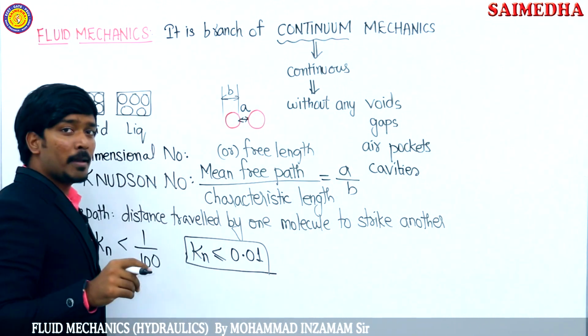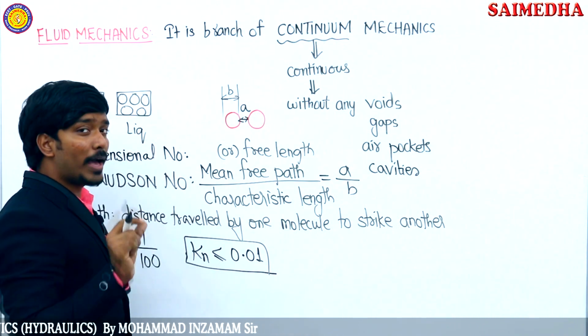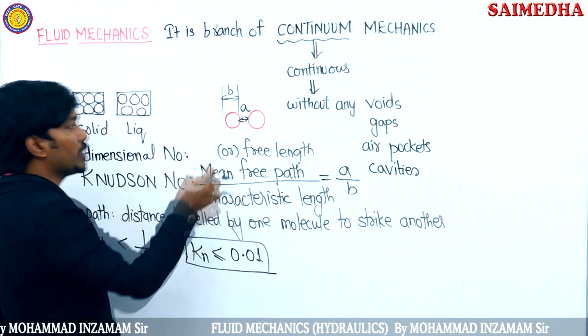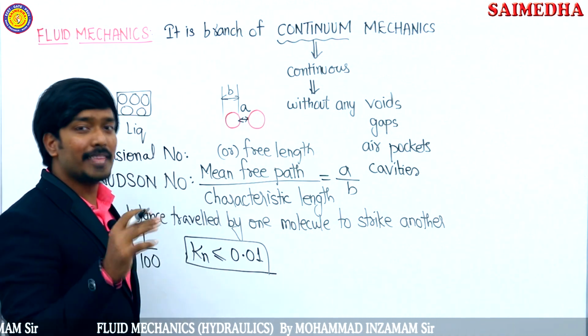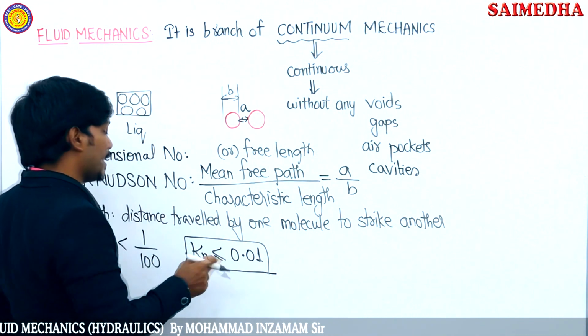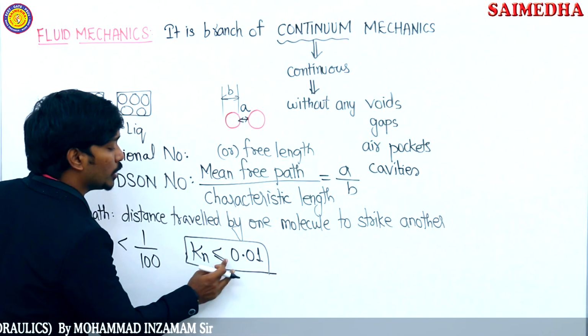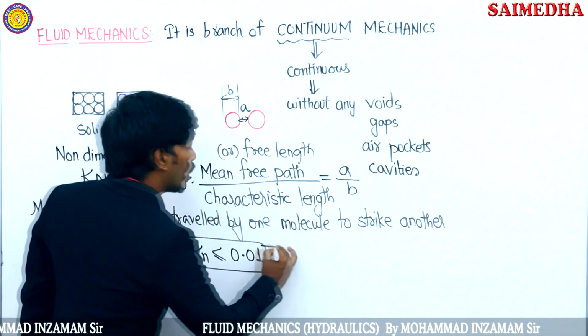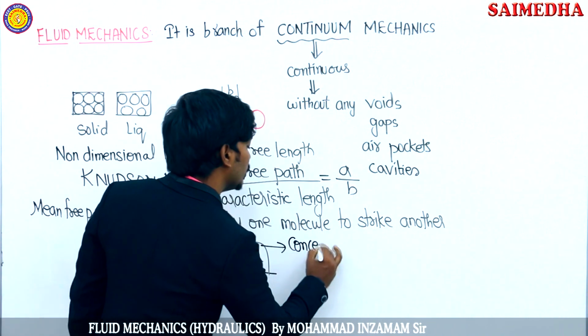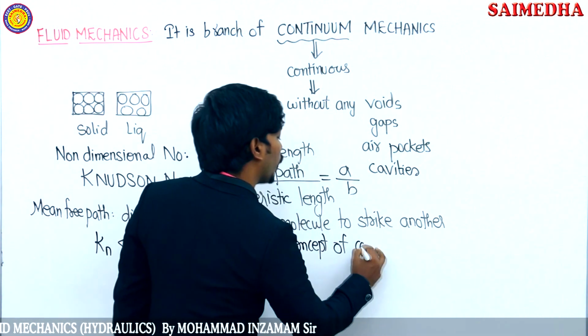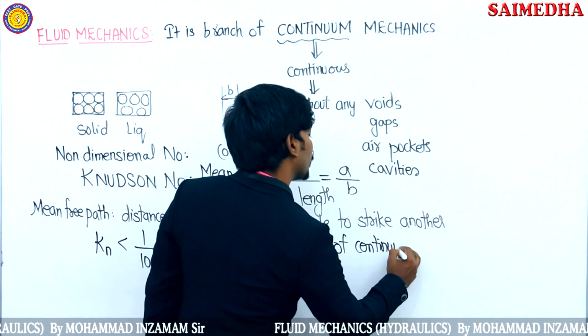You need to answer what? Based on the Knudsen number. If the gap value is 1 by 100th part of the size of the atom, the size of the molecule, then that can be neglected. And the value is Knudsen number less than or equal to 0.01. The concept of continuum holds good.